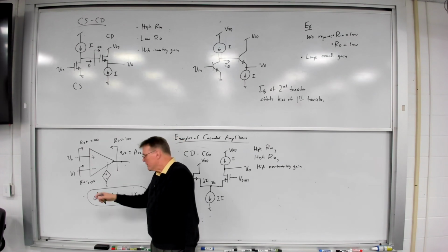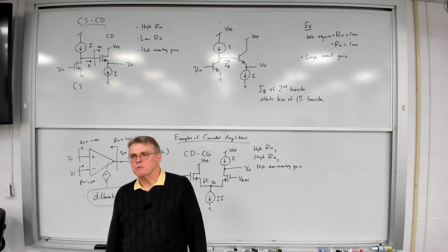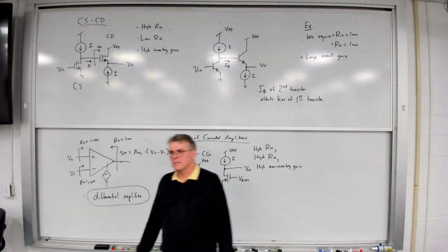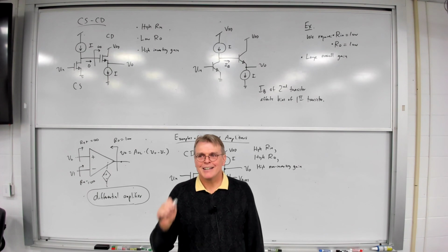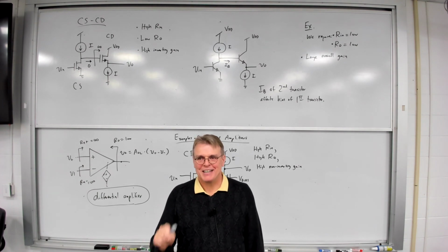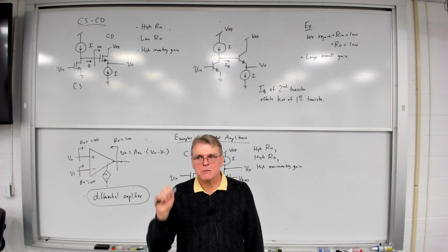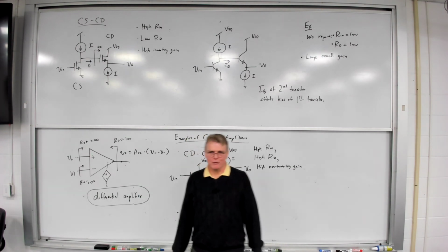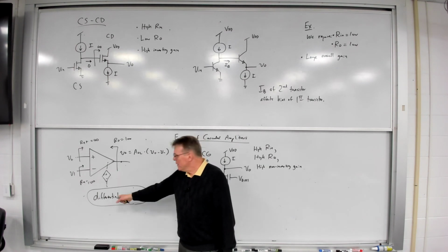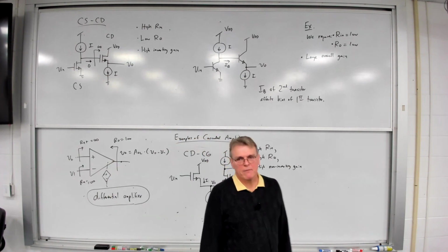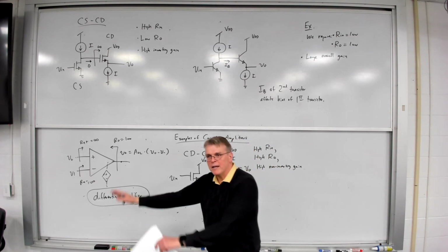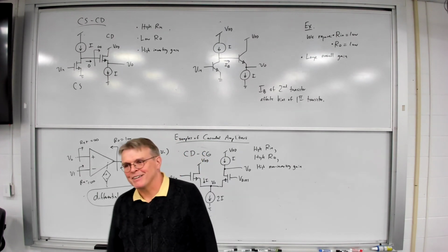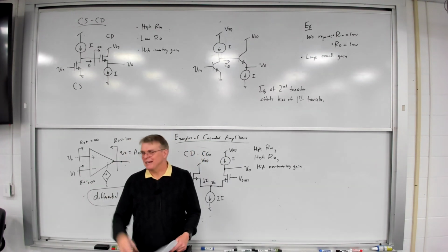And it turns out, we're going to look at this next time, the differential amplifier has a really interesting property. Not only does it let us amplify the difference between 2 voltages, it also allows us to get rid of bypass capacitors in an IC design and create a small signal effective virtual ground, which is incredibly useful in IC design. So next time we will look at that final stage, the differential amplifier, and then we'll put everything together we talked about today with the differential amplifier, and we'll design an op amp. All right, and that'll wrap this class up. Okay, I'll see you on Thursday.